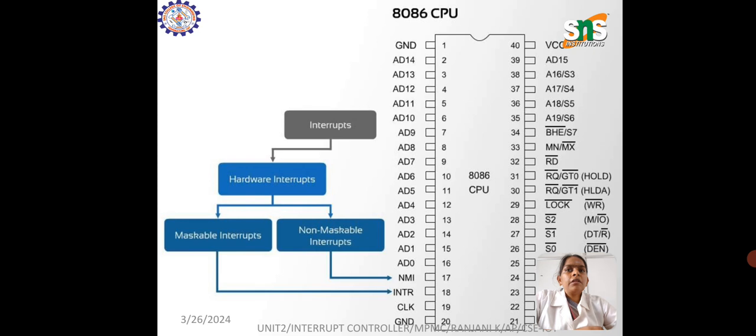So this interrupt controller is particularly programmed to reduce the burden of the CPU, and the interrupt controller is a programmable peripheral that enables and disables the interrupt request and selects the interrupt priority. As the CPU has limited hardware lines and computing, the interrupt controller extends the CPU for multiple interrupts by multiplexing interrupts with interrupts from peripherals.